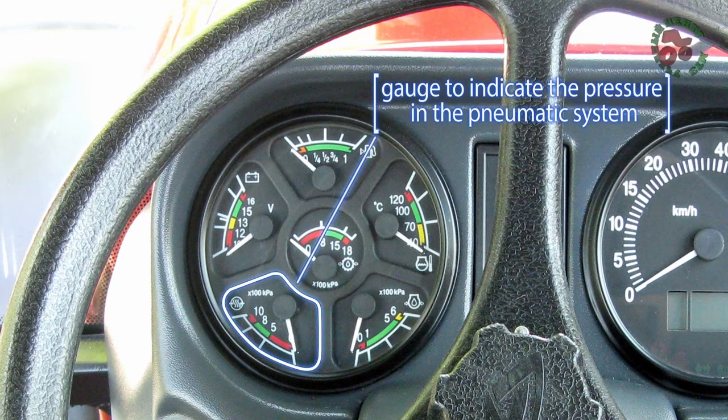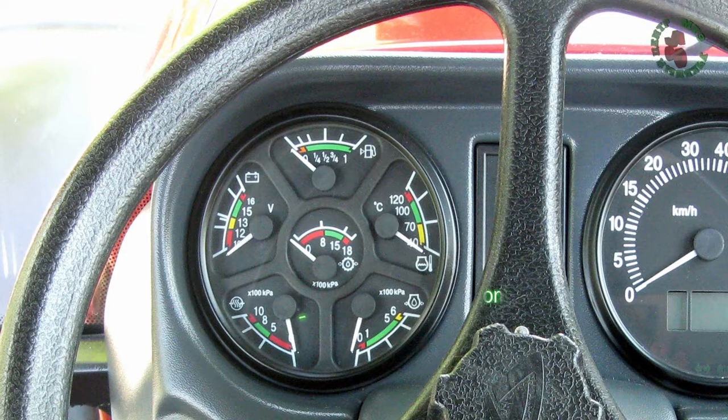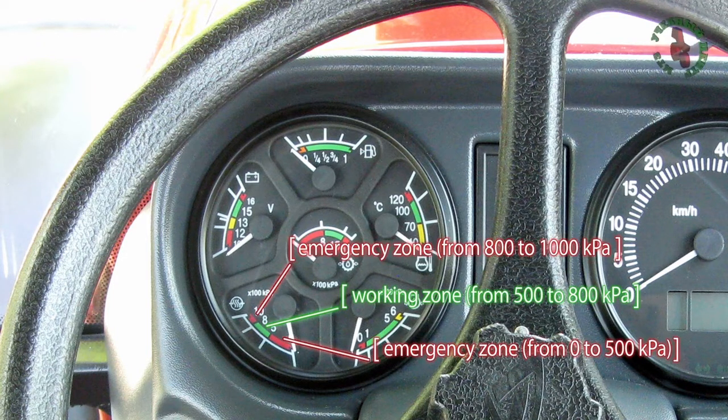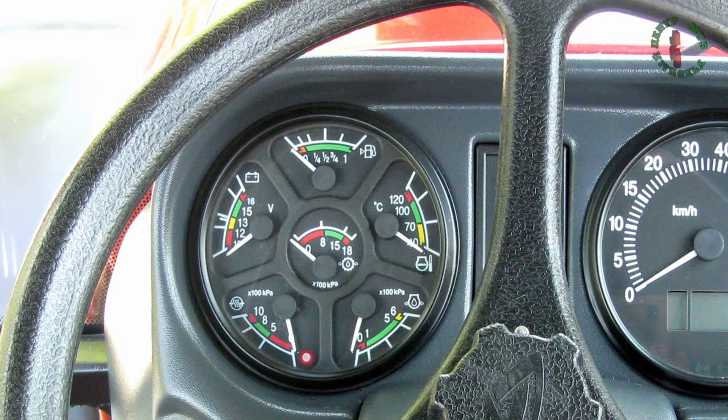Gauge to indicate the pressure in the pneumatic system. The scale of this gauge has 3 zones: working zone and 2 emergency zones. Pilot lamp of emergency air pressure in the pneumatic system lights up at pressure reduction less than 500 kilopascals.